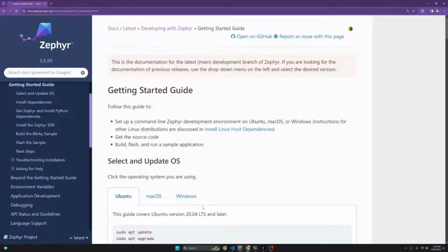If you go through all the setup instructions, you will end up installing what we call the Zephyr SDK, which provisions pretty much once and for all the toolchains, like the ARM GCC and Xtensa GCC for ESP32, and all those tools for being able to actually build code.